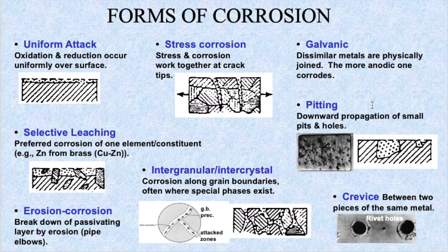There is also pitting corrosion. This is the one that you would find in most cases on the coastal areas where there is a salty environment. So the way it happens is that there are salt ions in the atmosphere that attack pieces of metal in such a way that the metal will have pits and holes in them like that. So that is called a pitting corrosion.